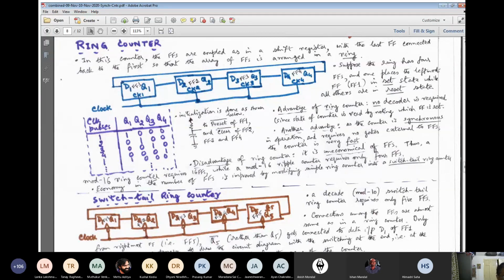As soon as you switch on the power, this RC circuit will tend to affect the state of the flip-flops, but only instantaneously, for a few instants right at the beginning of the circuit operation. After that, it will be the normal circuit operation under the governance of the clock. That will go on.